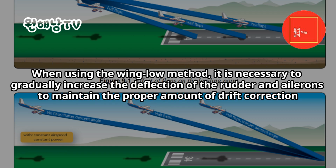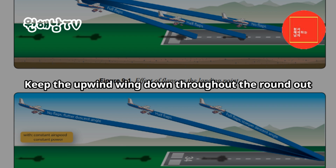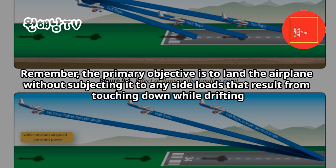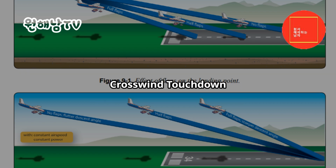When using the wing-low method, it is necessary to gradually increase the deflection of the rudder and ailerons to maintain the proper amount of drift correction. Keep the upwind wing down throughout the round out. If the wings are leveled, the airplane begins drifting and the touchdown occurs while drifting. Remember, the primary objective is to land the airplane without subjecting it to any side loads that result from touching down while drifting.